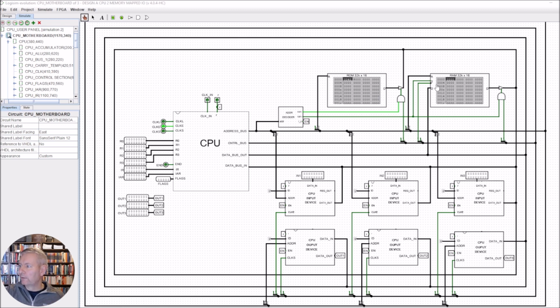Now we do the same thing with the RAM for the enable. So the RAM enable comes along here, and we've got it going into this point here, and we have the enable being pulled off here, which is pin 0. And when these two go high, we're going to be reading information out of the RAM onto the bus, and that bus, it goes back into the CPU.